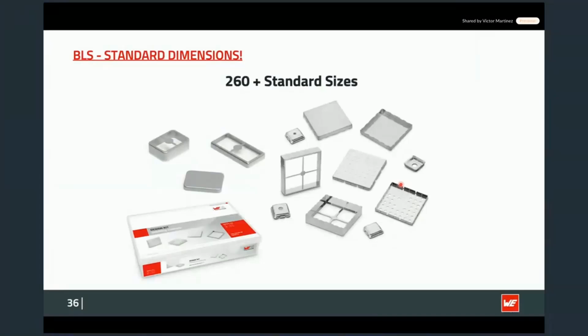But at the end, we are working metal, and working metal is not a cheap thing to do, meaning that there will be some cost needed here. That's something that normally is not suitable, especially for samples. So the advice here is to keep in mind that you will probably need a shielding cabinet from the first time. So add the footprints already to the areas which you think can be a bit sensitive or problematic.